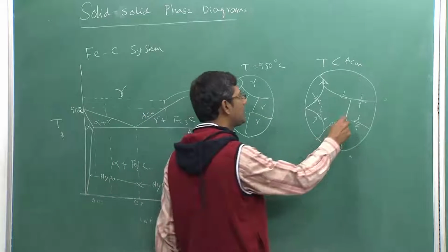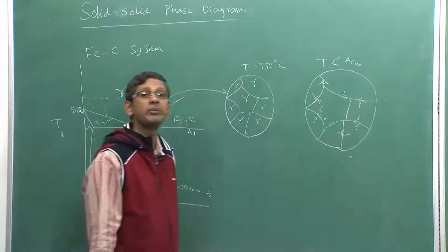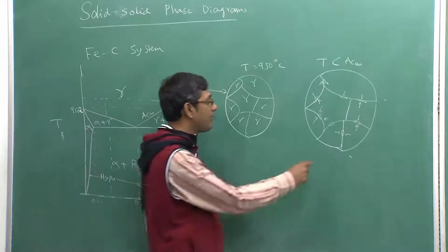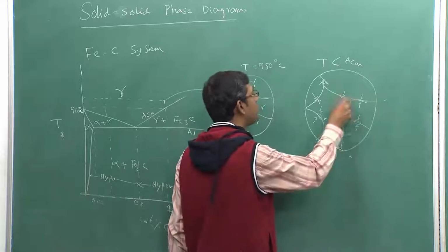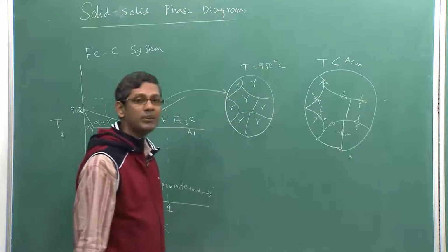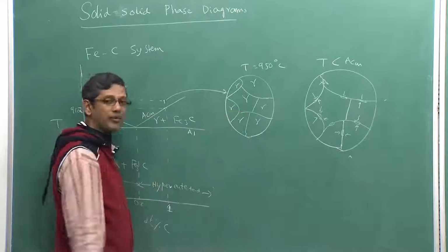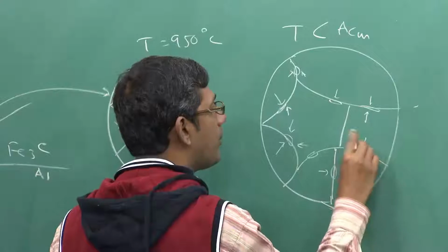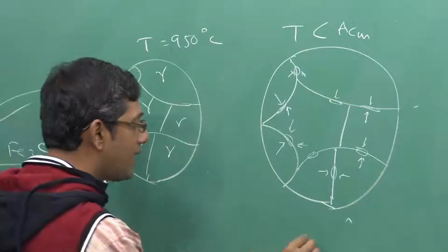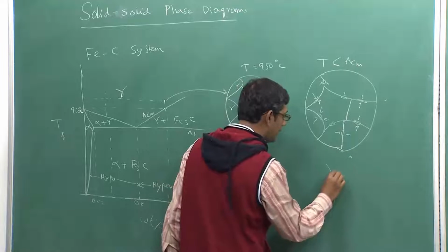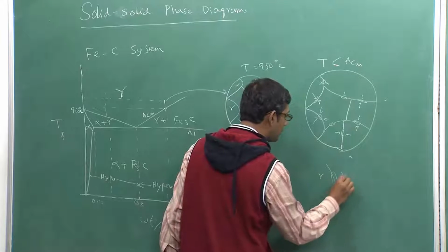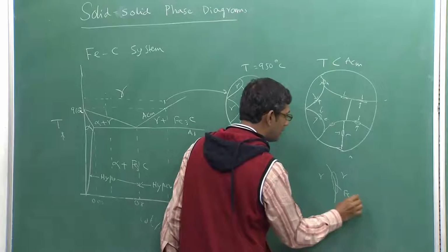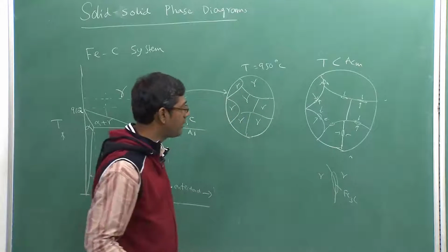These are the reasons why diffusion of carbon can happen very fast along the grain boundaries, and that is why the cementite nucleates on the prior gamma grain boundaries, and then the cementite lamellae will grow along the grain boundaries. That means they will lengthen along the gamma grain boundaries, because of the faster diffusion path.